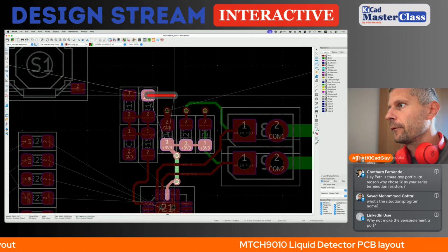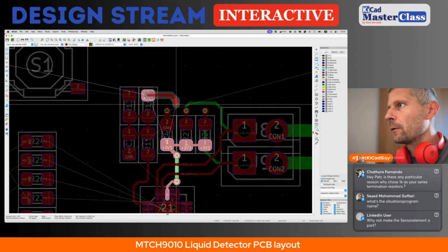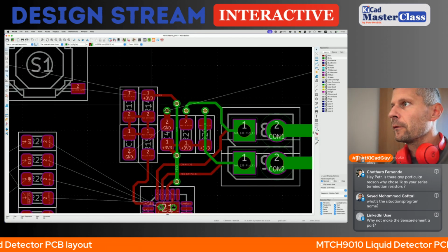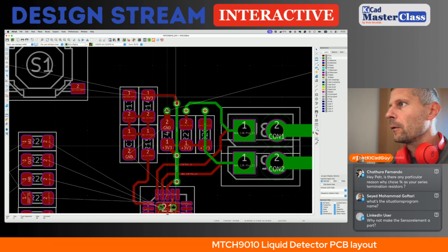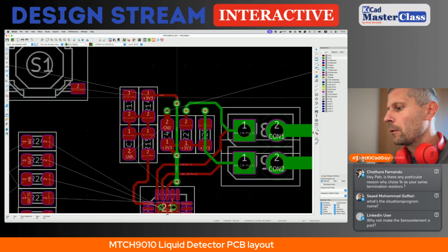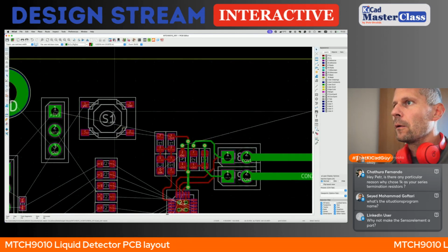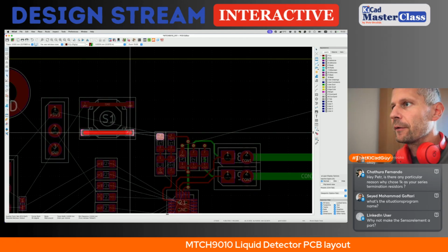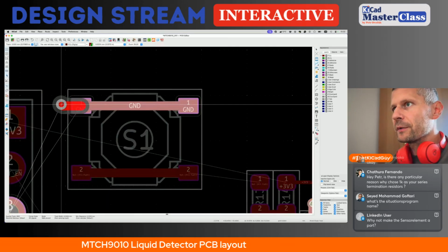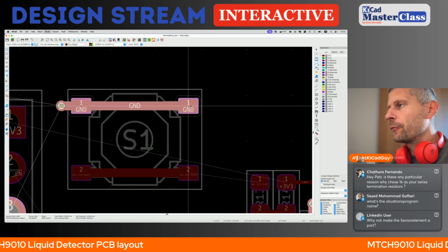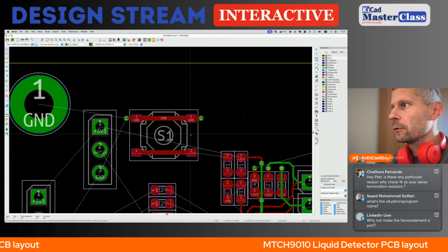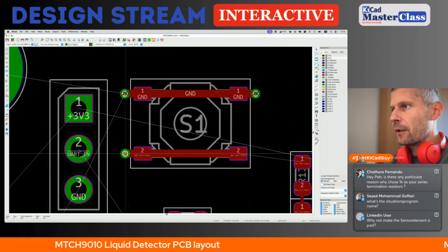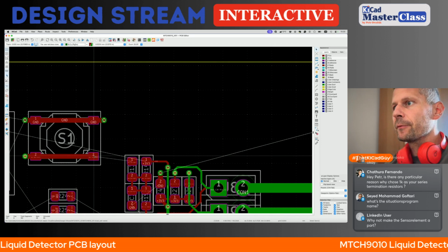3.3, using the via as well. I want to use the thick tracks here to provide some firmness of the bottom of the button connection, even for the price that there will be some ERC or DRC findings.